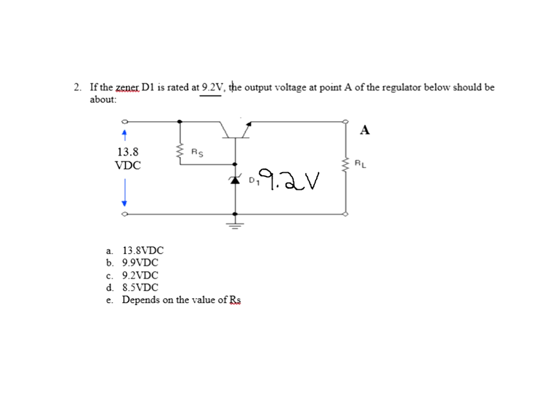Now look at these answers. They got a lot of distractors here. Is my answer going to be 13.8 because I'm putting 13.8 in? Is it going to be 9.2 because I'm getting 9.2 on the Zener? Because one of the tricky questions on the exam is, what is the purpose of a Zener? The purpose of a Zener is to conduct so that the voltage across the Zener equals the Zener voltage. One of the other distractor questions on there is it regulates all circuits at the Zener voltage. That's not true. It conducts to limit its voltage to the Zener voltage, not that it regulates at that voltage. But anyhow, that's another question. You'll see that later.